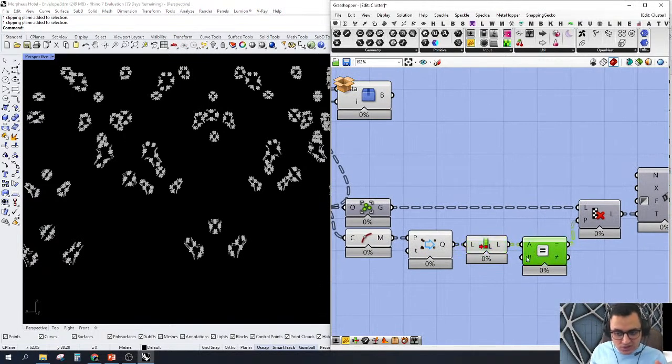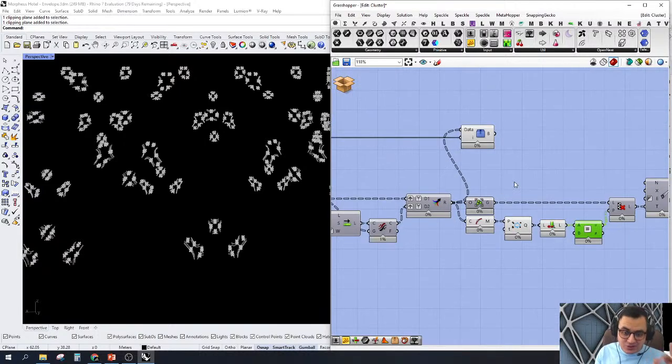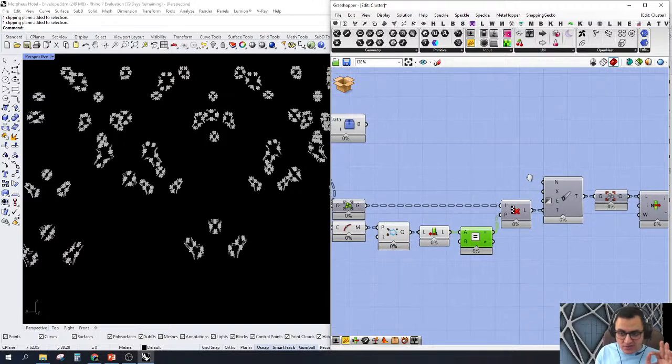And of course this is just 2. If the list length is equal to 2, bring it. If it's more than 2 elements or less than 2 elements, I don't want it. I wanted the list length of these curves to be exactly 2, so I will make sure that they are perfect.